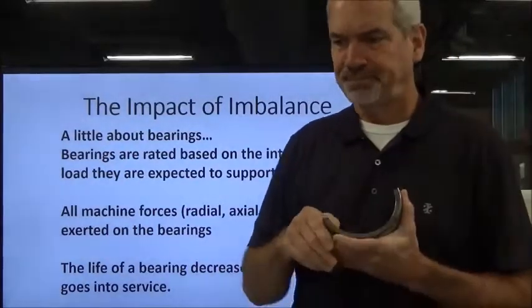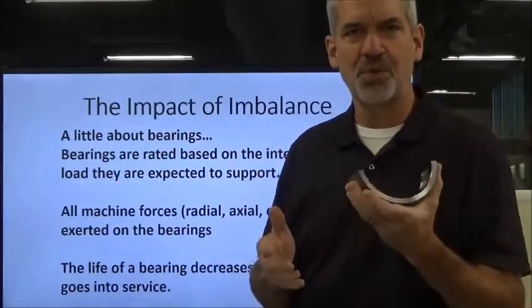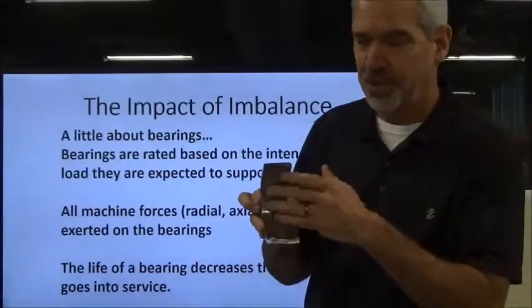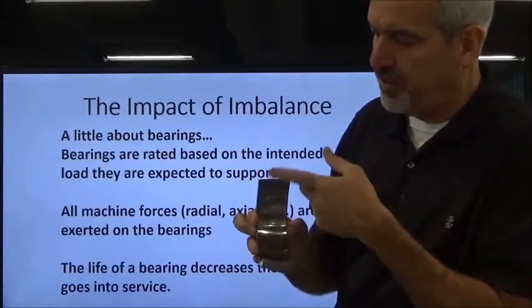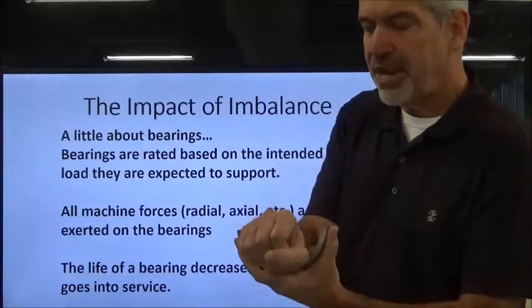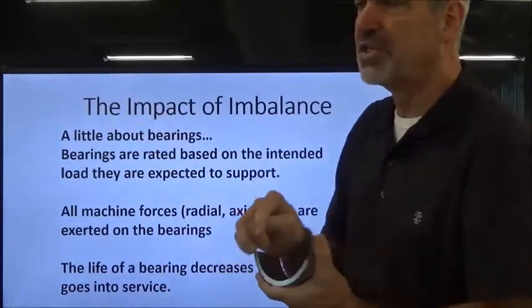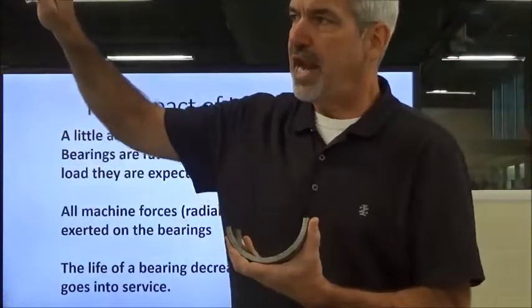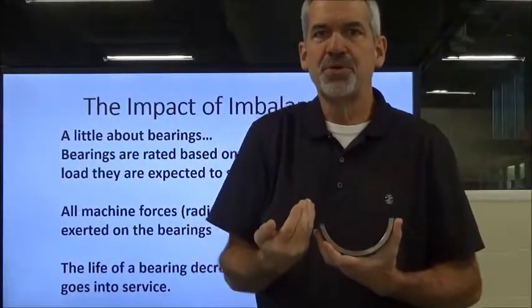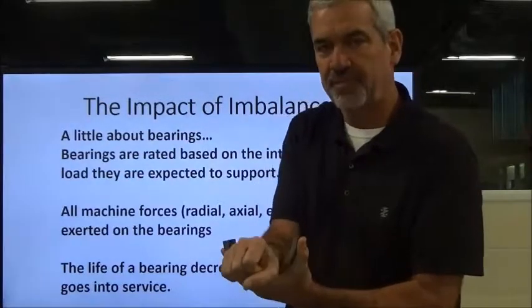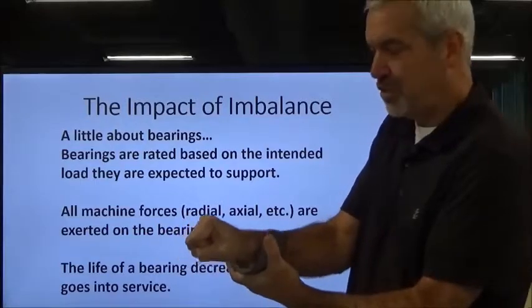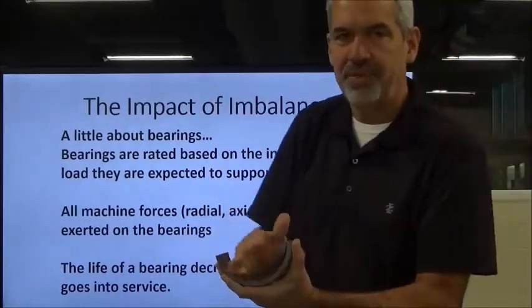And as it turned out, we took it to the shop, figured out what's going on with this bearing. Well, we cut it open, and you can't see this in the camera, I'm sure, but there are little etch marks on the outer race of this pillow block bearing. And that shaft sat in there over the weekend. Remember, you have 4 other fan units, and they are vibrating, and that vibration is transmitting through the floor up through this idle machine, this sitting idle. And the vibration was causing the shaft to move, to jump up and down inside this bearing.